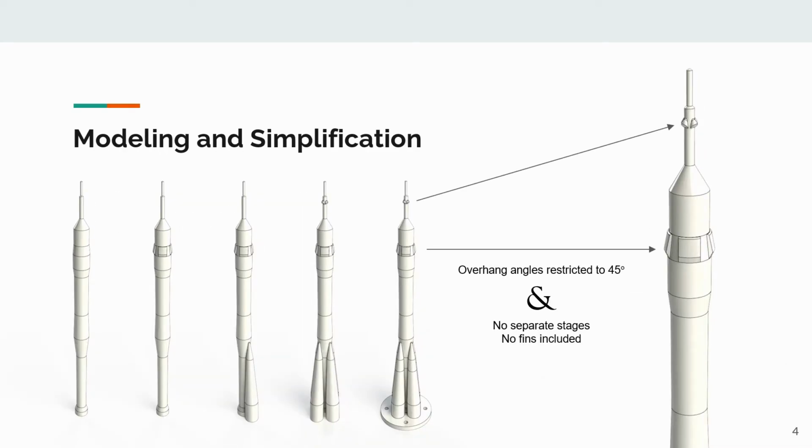To design the model, we used SolidWorks in conjunction with the schematic shown a couple slides back. We scaled the schematic down such that the rocket height would be 2 feet according to our design constraints. Then we used the plane formed by the schematic to trace one half of the rocket, then formed a body of revolution shown on the far left. After adding some payload stage features, we placed multiple sketch planes along the axis of a booster in the schematic and traced the tapering cross sections as we moved up that booster. We connected the cross sections with the loft tool, then circumferentially patterned the booster to form 4. Then the remaining details were added.